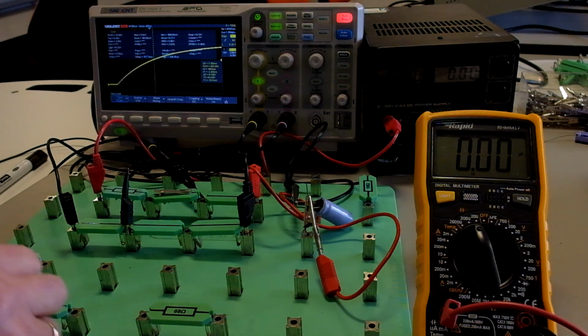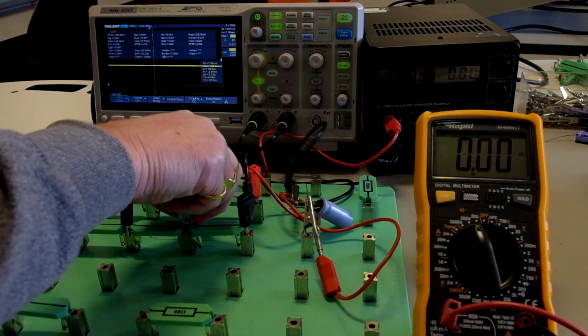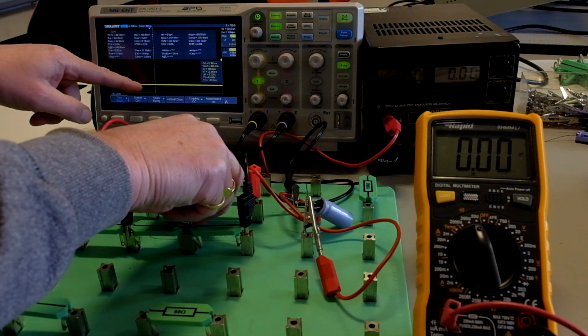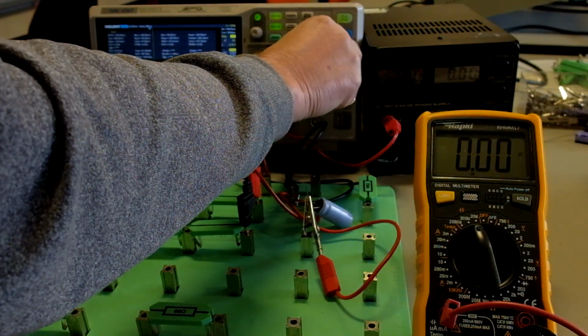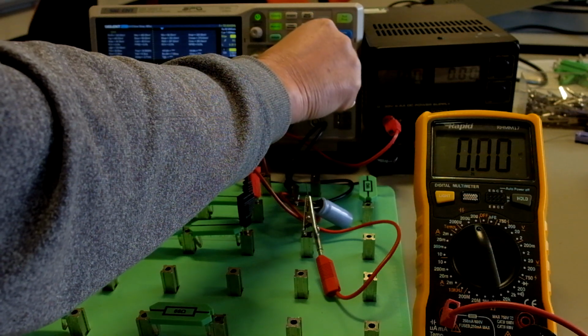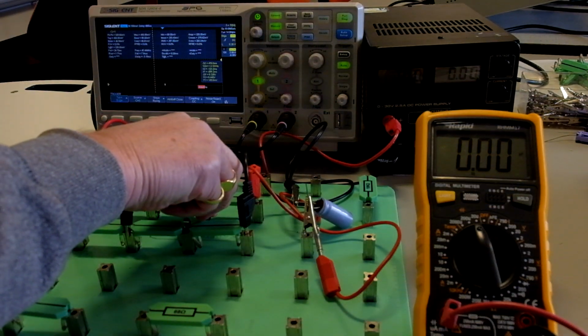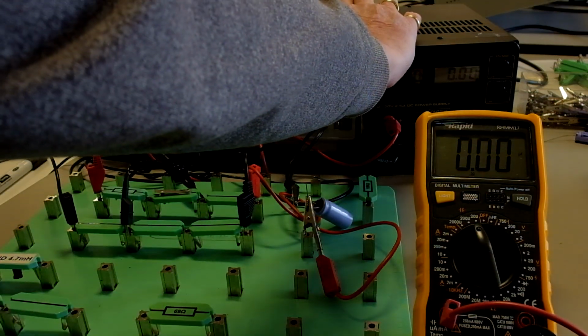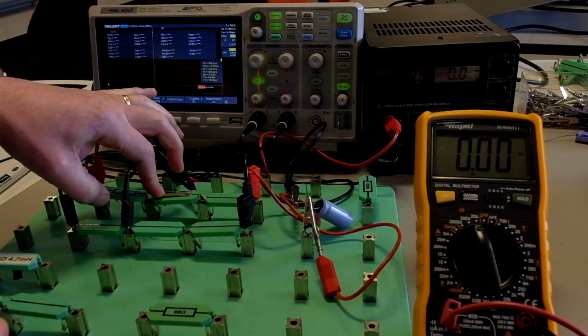What we will do is we'll put that onto auto. We'll discharge the capacitor down to 0 volts. We need to change the time base. Just double check it is 0. Put it on single shot. Acquire the charge curve.